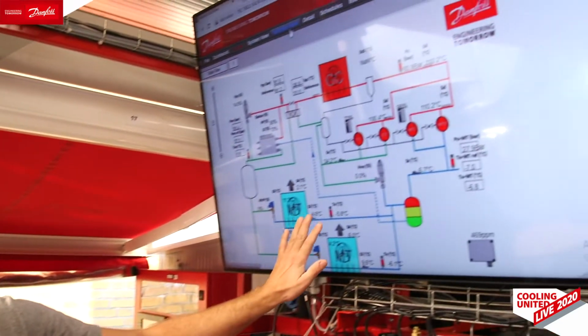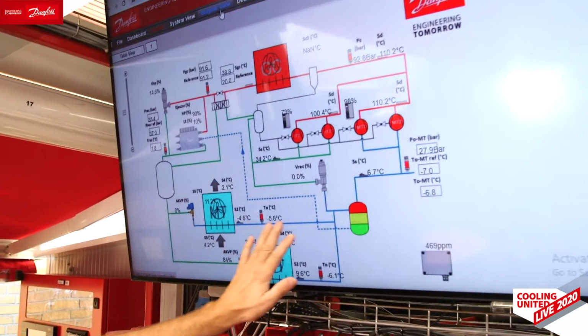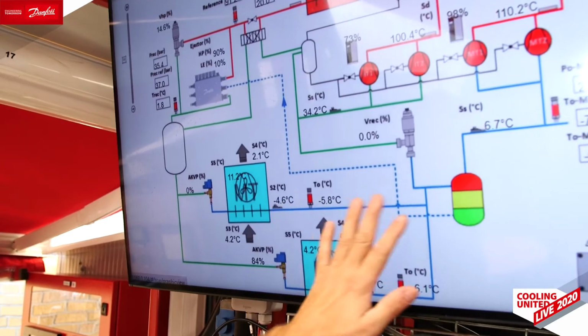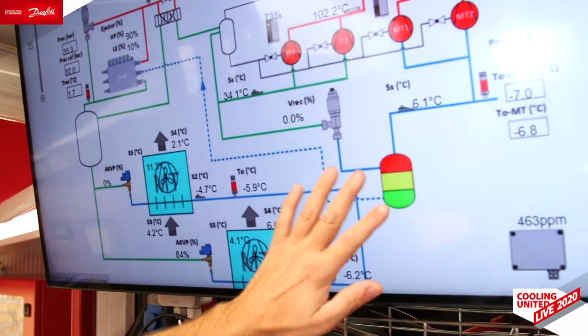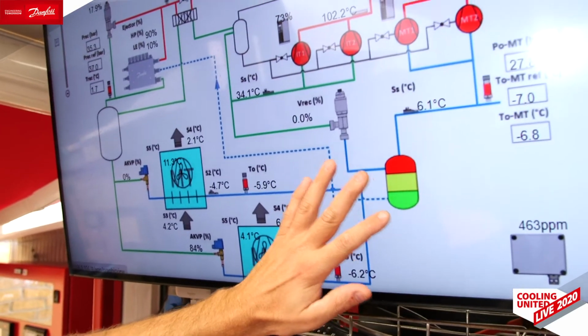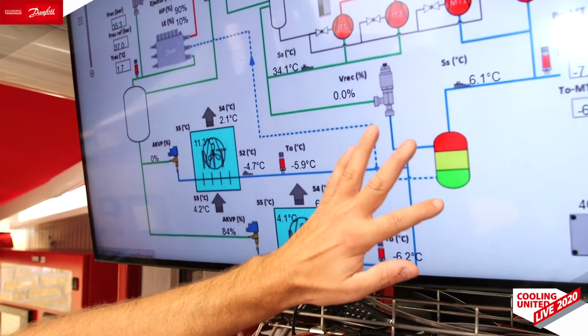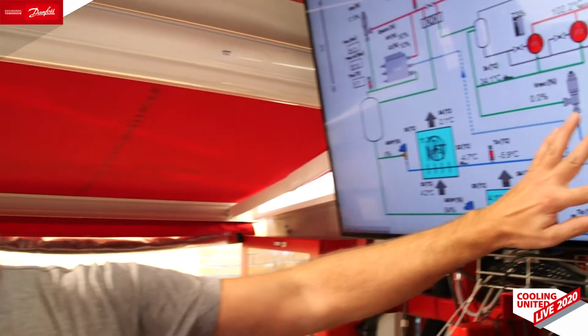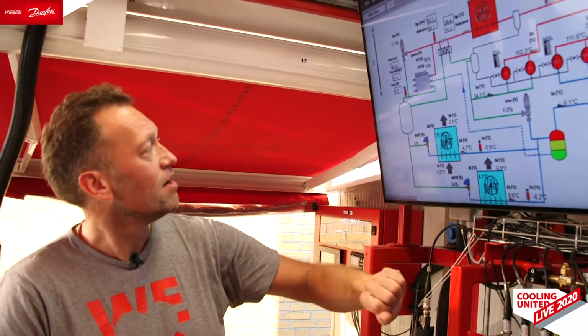or also from other systems that are used in commercial refrigeration. So we really have a system that delivers very, very little refrigerant. And this means that the suction accumulator, where we have the droplets coming out, the refrigerant coming back from the evaporator, can be dimensioned very small, and that means that this cost driver has a limited impact on the whole installation.